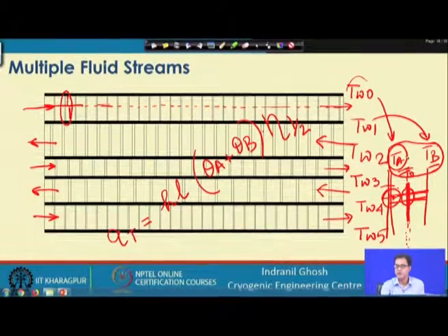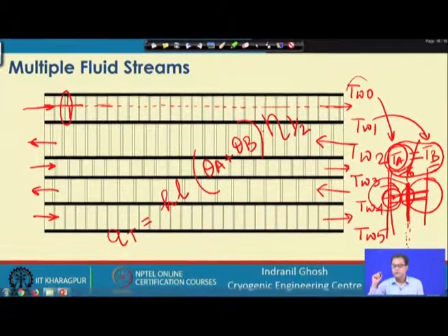So, half of the fin is as if attached to this plate and half of the fin is attached to this plate, but it may not be the situation for every case where T A and T B are not the same. Depending on T A and T B, we may find various kinds of configurations where the extremum, the minima or the maxima, is lying within the fin or outside the fin, and of course, it may be that there is no minima at all.